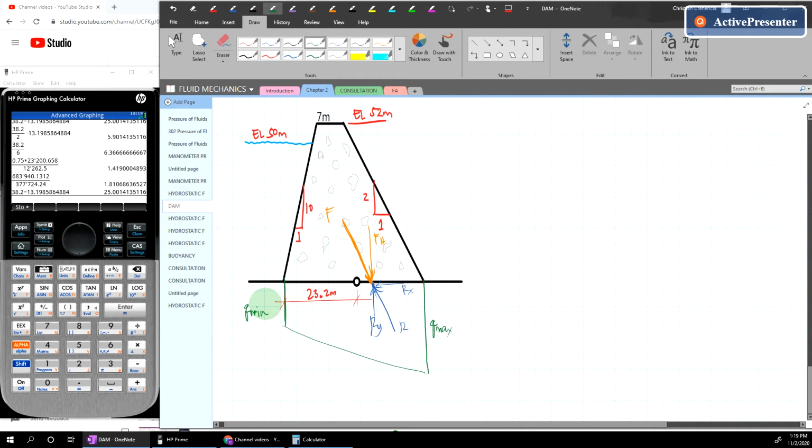Okay, so solving for the soil pressure Q. So again, that is yung Ry over nung width nung base nung dam over B, then multiplied by 1 plus 6e, eccentricity, over nung b. Okay, so again, may derivation na tayo dyan. So, plus or minus.